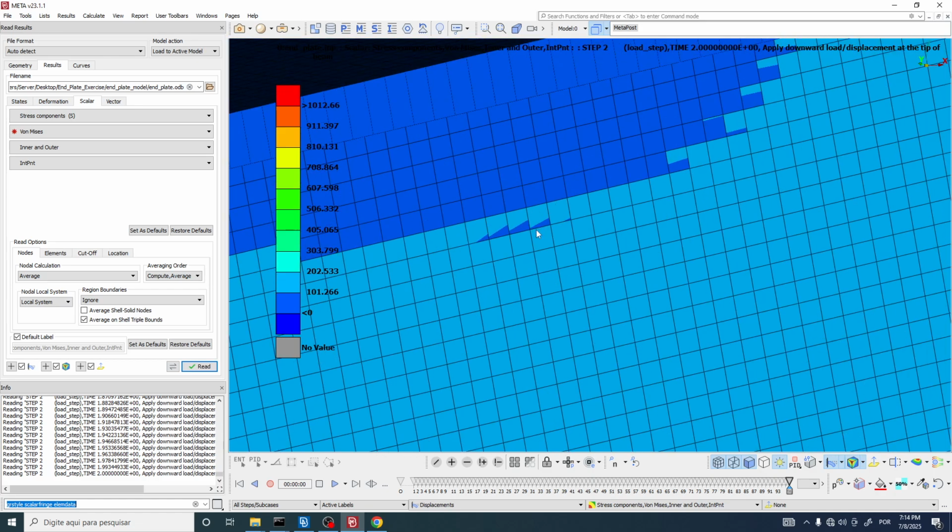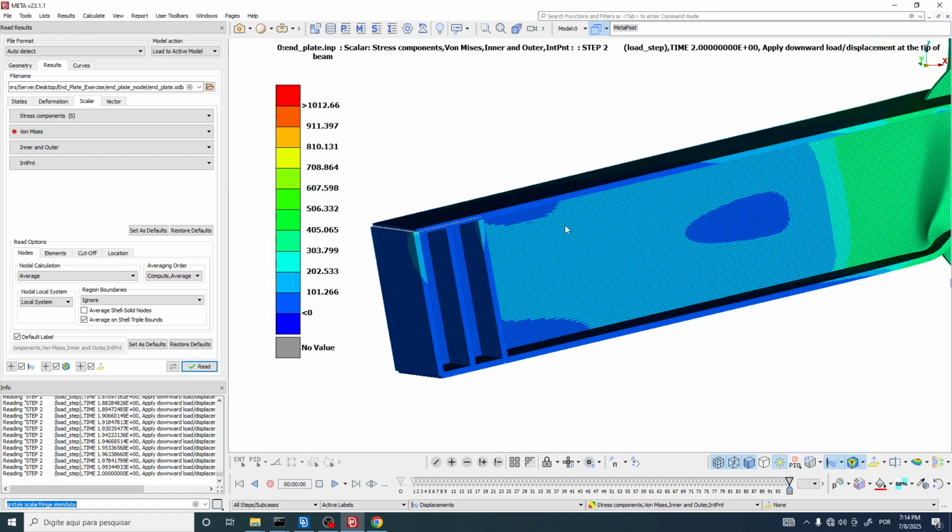And this is something that occurs in the solution of the mathematical model using FEM. Okay, we don't have continuity in the strain field, and obviously in the stress field as well. We have continuity only in the displacement field.